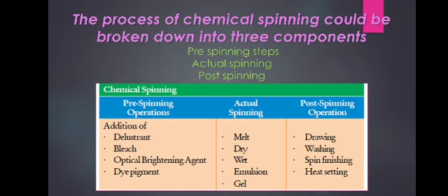Polyester and nylon are manufactured by the melt spinning process. Cellulose acetate is formed by the dry spinning process. Next is the wet spinning process. It is the oldest, most complex, and most expensive method of man-made yarn manufacturing. In this, a non-volatile solvent is used to convert the raw material into a solution, and this is passed through a bath solution where it solidifies.